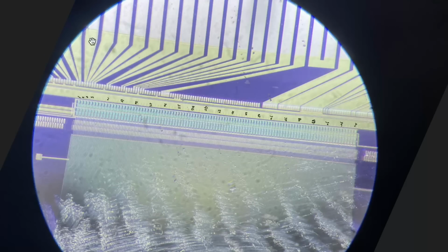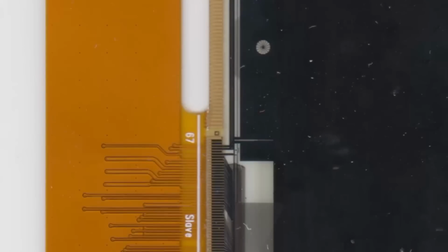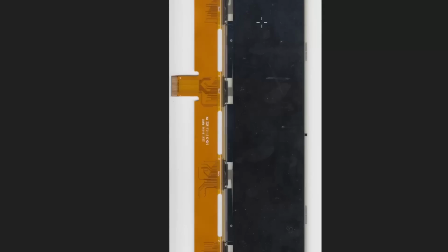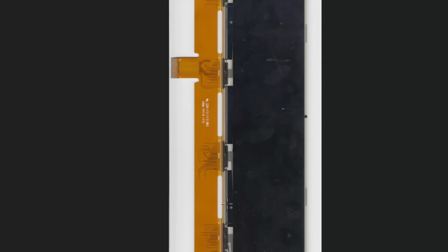So the real resolution is 300. This screen is definitely not making use of every possible pad. For example, here we see only about 120 pads are being connected. So the width resolution using one chip is 120, and we see two of the chips connected, so it's 240. That already gives us the full screen resolution: 400, 400, 400, 400 on the x-axis, then 120, 120 on the y-axis. So the whole screen resolution is 1600 by 240.